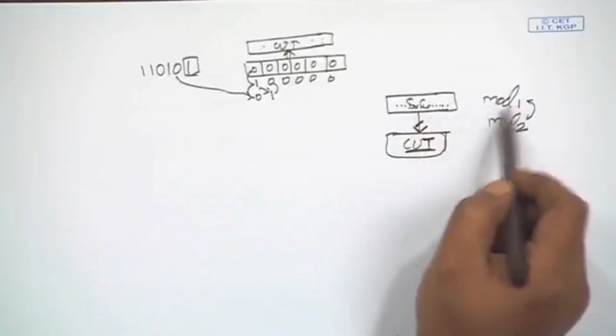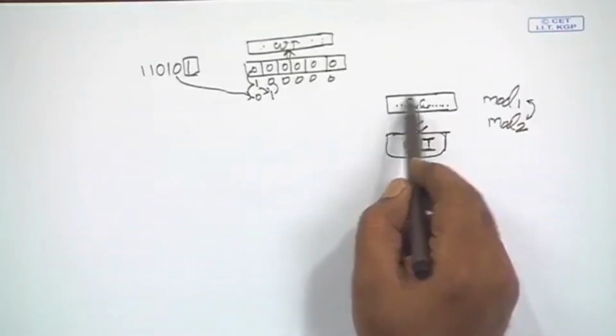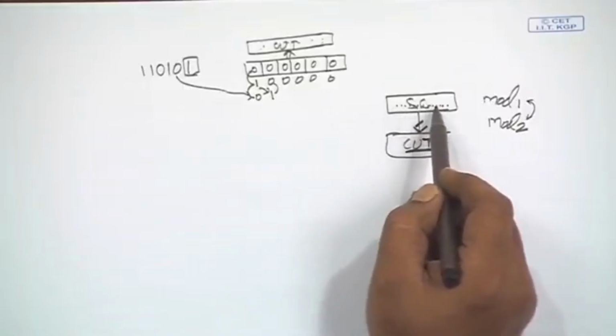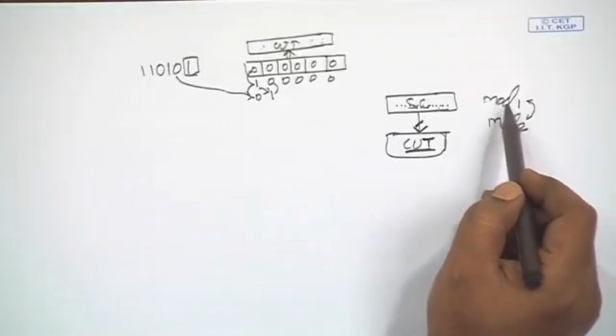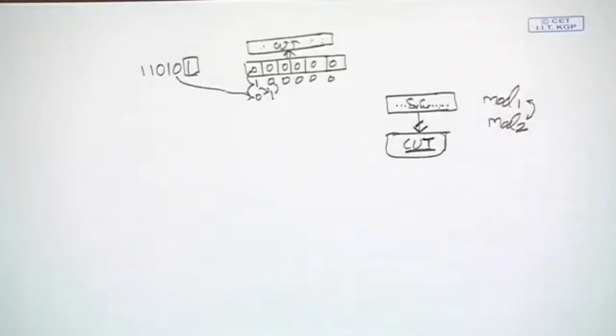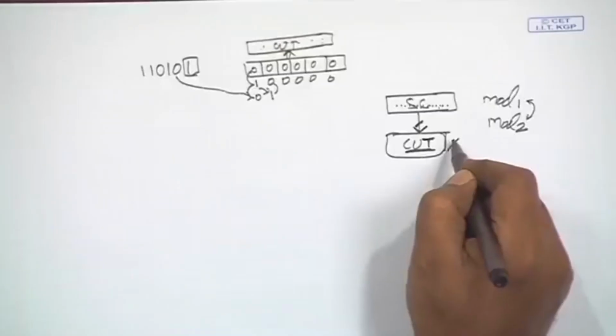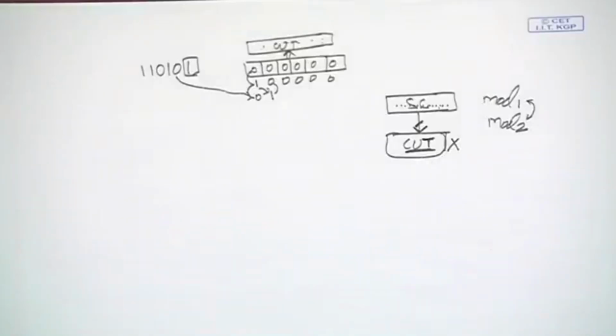So, if we see that in the scan chain there are more transitions in modification 1 than in modification 2, then the circuit under modification 1 is expected to consume more power than the circuit under modification 2. So, we do not need to do explicit logic simulation of the circuit.